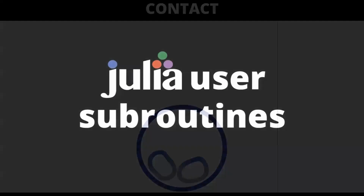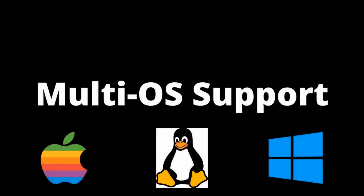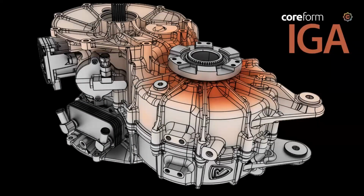It supports contact, both self-contact and surface-to-surface contact. And so you can see here with this little toy problem. We also support Julia as our user subroutine interface, which makes it a lot easier to write things like a custom user boundary condition or even user materials. And as you saw in that last little part, we support the 3 major platforms: Linux, Windows, and Mac. Our goal is to be able to run these complex analyses on complex parts without having to defeature and spend the time to do that.